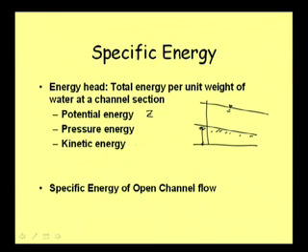So, from that point of view, the pressure energy in open channel flow comes as y, but of course, when there is a slope theta, we can write it as y cos theta, as was discussed. This theta is basically nothing but the slope of the bed, that is S_B, the bed slope. Well, then kinetic energy. That is again half m v square, and when we derive that expression for unit weight of fluid, we get v square by twice g.